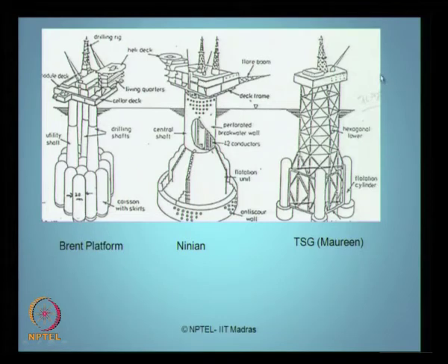All of them have very large and comfortable deck topside activities. These platforms are very stable under lateral loads. Look at the common structural members of these kinds of platforms. They have all common operational systems like helideck, double deck system, housing quarters, flare booms, drilling rigs in almost all of them.